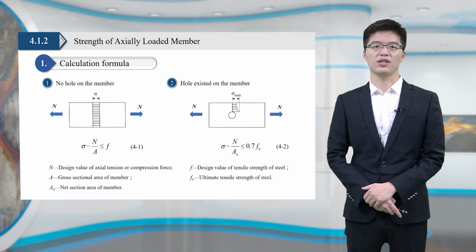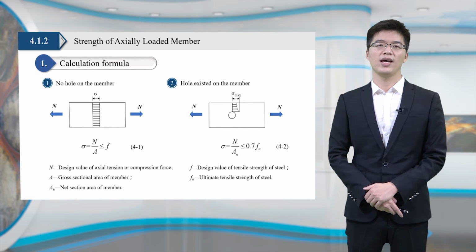Deformations continue with increasing load until finally the rupture of the member occurs when the entire net section of the member reaches the ultimate stress Fu. The design strength of axially loaded members due to net section rupture is given in equation 2.